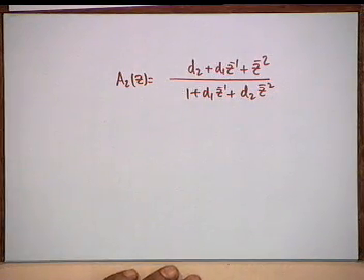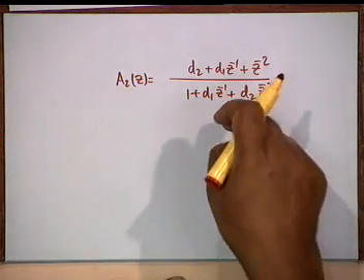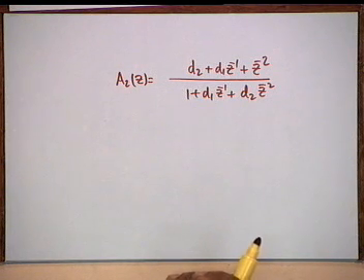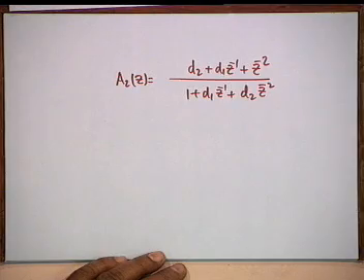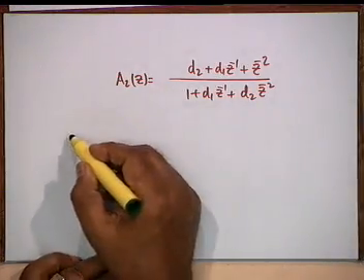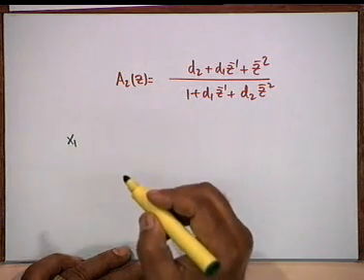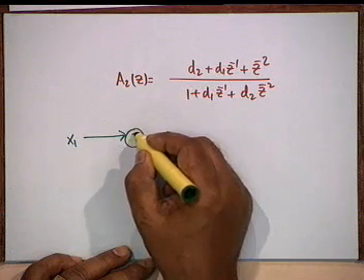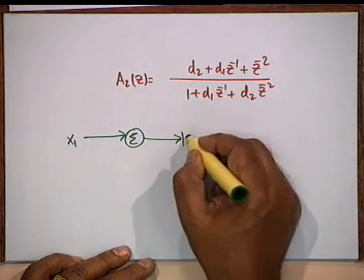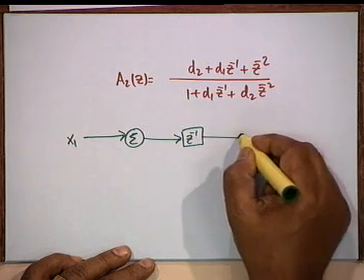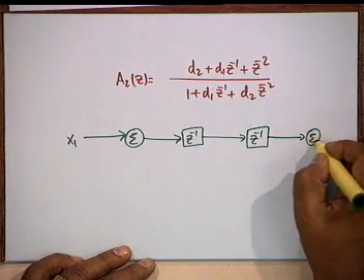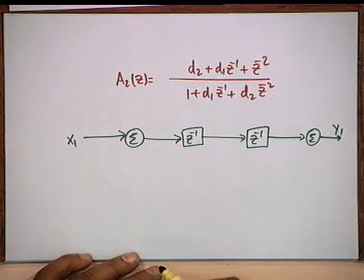I didn't take this form to start with because derivation of the other one is easier than the derivation of this. This can also be realized with only 2 multipliers, and the realization, please draw with me, is as follows. But it's slightly more involved to find out this structure. I encourage you to find this structure. x1, it is very similar to the previous one, z inverse, and finally a summer output y1. This is what we draw at the beginning.